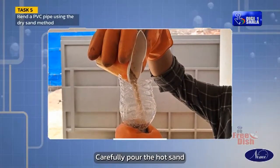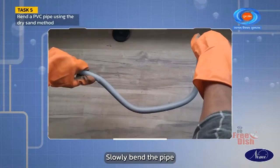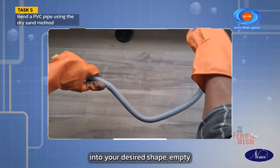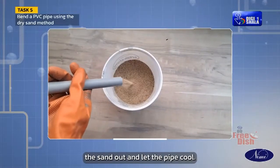Carefully pour the hot sand back into the PVC pipe. Slowly bend the pipe into your desired shape. Empty the sand out and let the pipe cool.